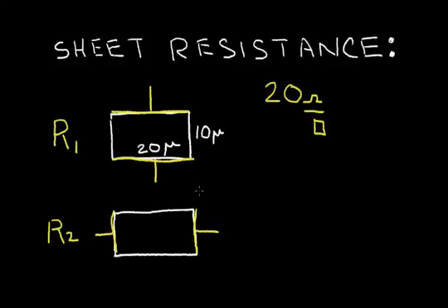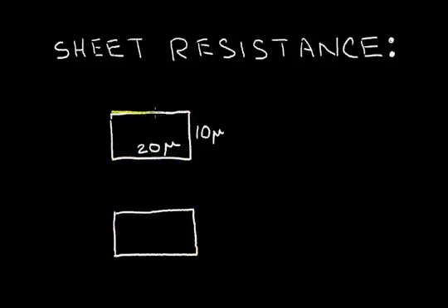I'll give the solution. Okay, I presume that you've given this a shot, and let's see if we get the same answer. So recall that resistance is equal to the sheet resistance, R sub S, times the number of squares, which is the length of the resistor divided by the width of the resistor. Along the top surface, I want to form a resistor terminal in this direction. And I want to connect along the bottom surface and form a resistor terminal this way.